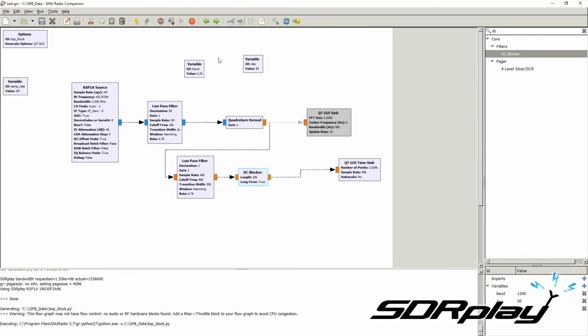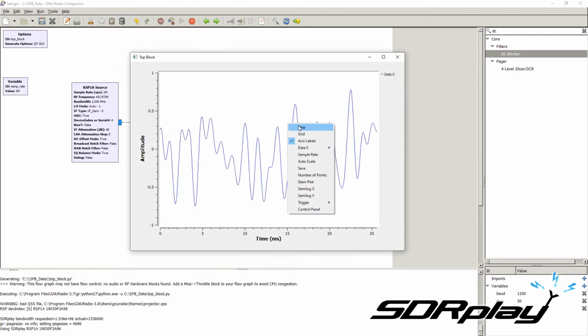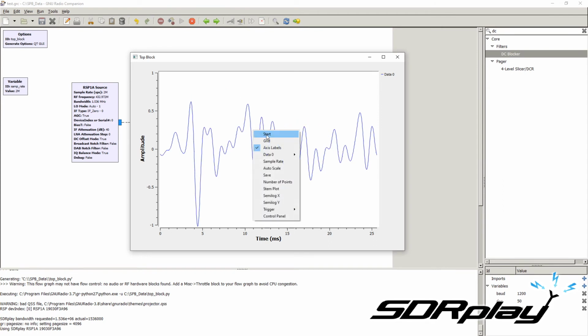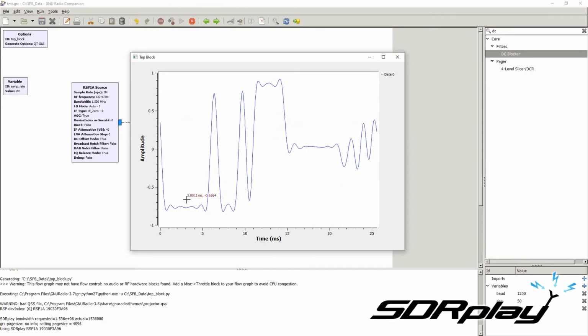One thing that we notice is that this signal is not a square wave. It is actually very rounded. This could be a problem because we want to receive a square wave. But by cutting off higher frequency, we actually made it impossible for this to be a square wave. So we want to do some manipulation to make it a square wave.